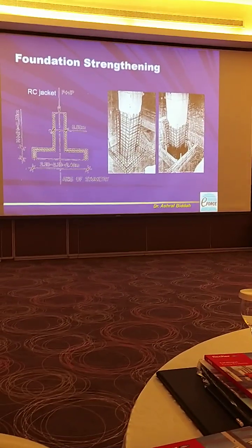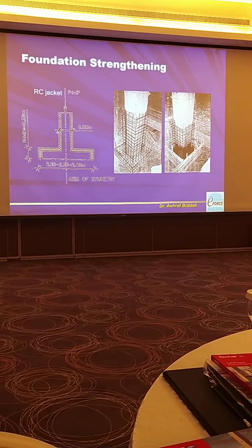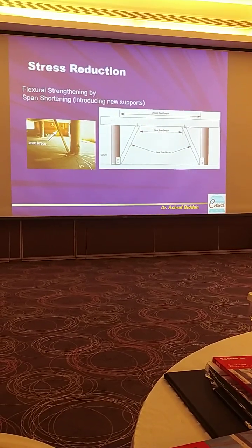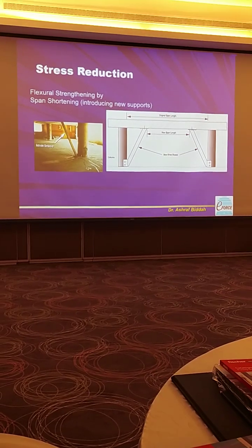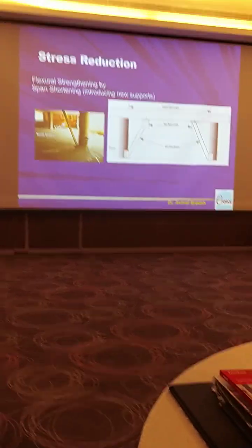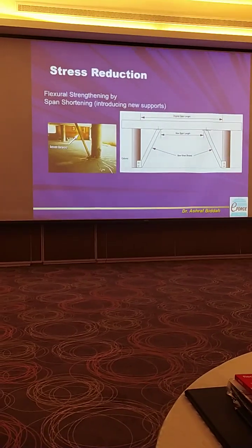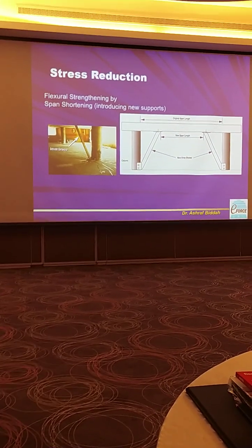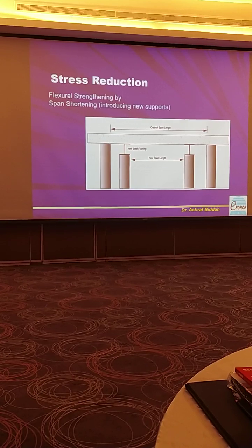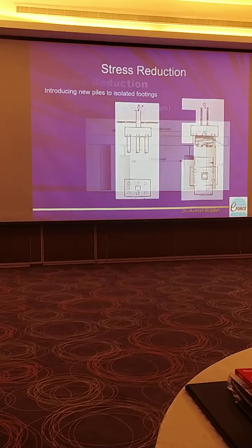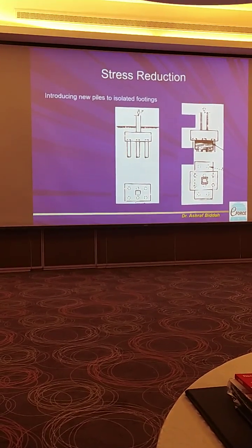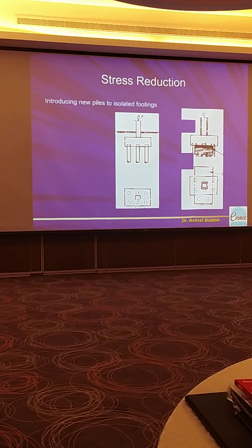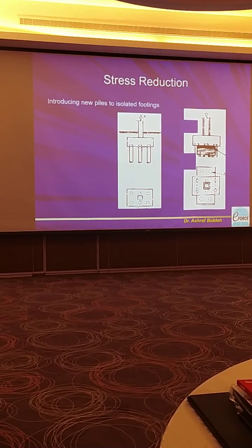Foundation strengthening by increasing the dimensions. Or another solution by reducing the stresses. If you have a large span, you can reduce the span, so that will reduce the bending moments, or by having more supports. Increasing the capacity by adding more piles.